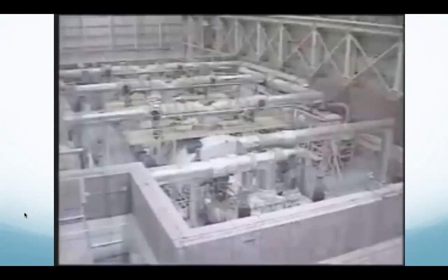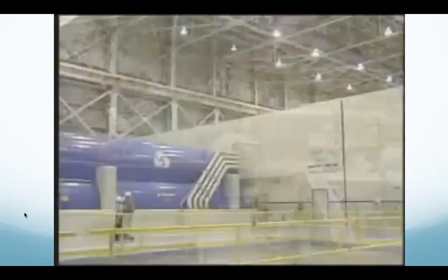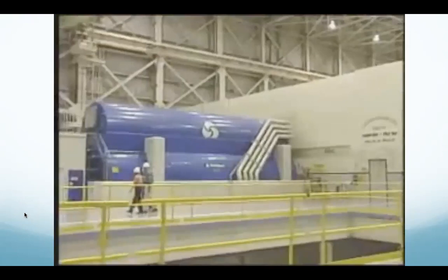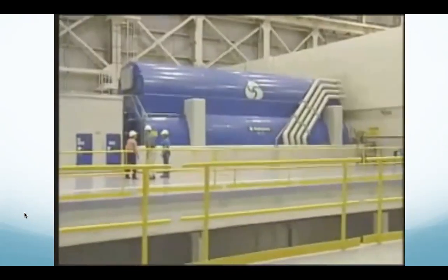Steam from the reactor vessel is used to turn 4 large turbines, which are attached to a large generator. Together, they turn 1,800 times each minute, producing enough electricity to power a city the size of Seattle. When the steam leaves the turbines, it's turned back to water in a special heat exchanger called the condenser. The condenser has thousands of little pipes just like this one. Each pipe is filled with cool water from the Columbia River. When the hot steam touches the cool pipe, it condenses back to water.